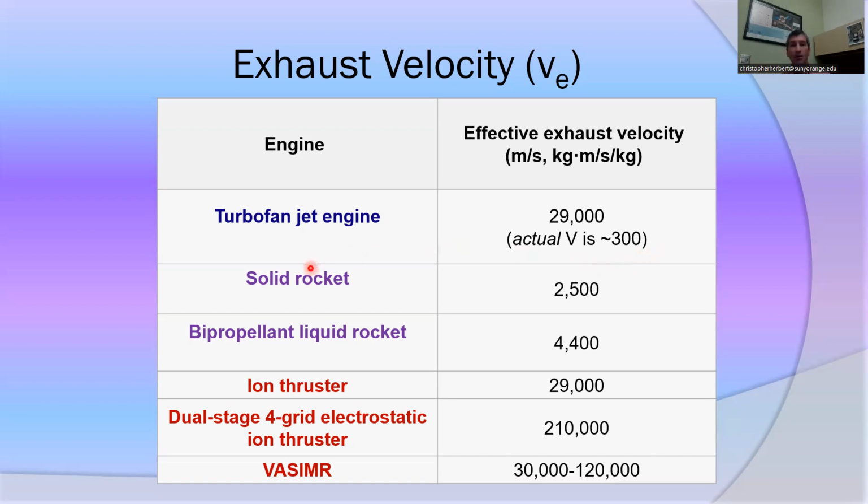Okay. So when we are talking about rockets, there are different types of rockets that produce different types of effective exhaust velocities. What you'll generally see are solid rockets used to boost the rocket in the initial startup phase of the launch. These are not very effective once we get past the initial velocity, but they can produce a tremendous amount of thrust and take up most of the workload on the first phase of launch.